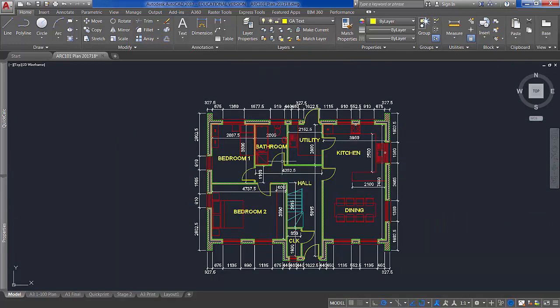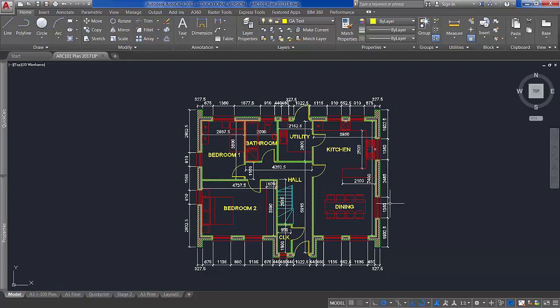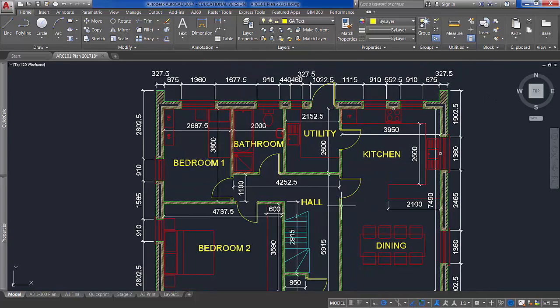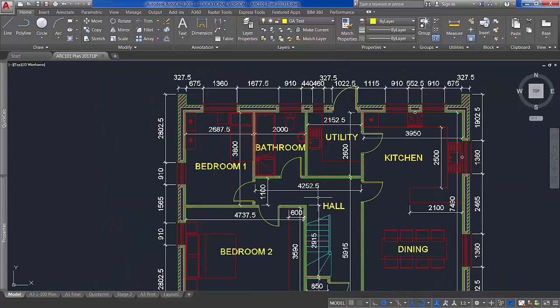So a few general pointers in terms of what you need on your building control style drawings. Obviously all your internal furniture, your structure, all the openings, appropriate hatching for all of these different things, and try and use some line weights to distinguish between the different materials. So things like the walls should have a heavier line weighting compared to the furniture or even the lines that indicate the stairs there. And then also you need to clearly mark the location of any beams or anything like that.